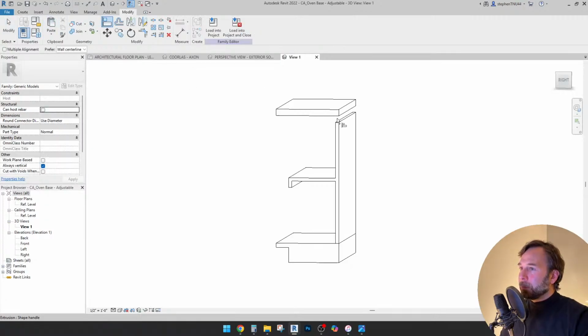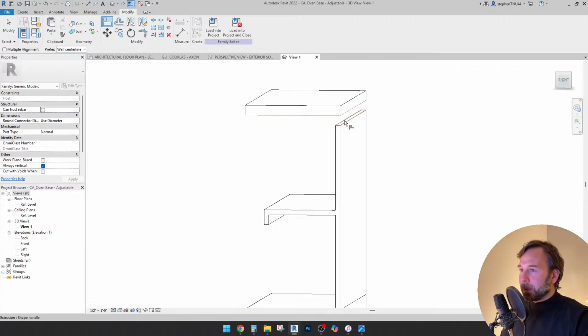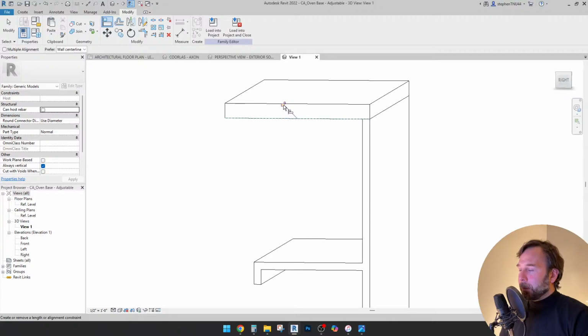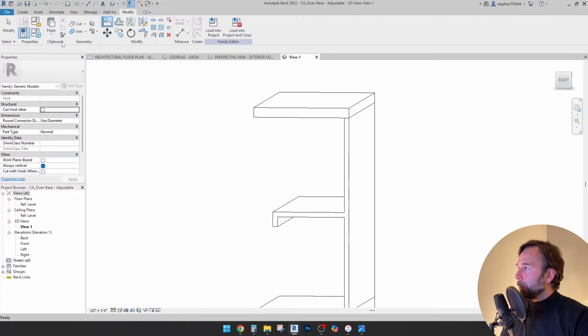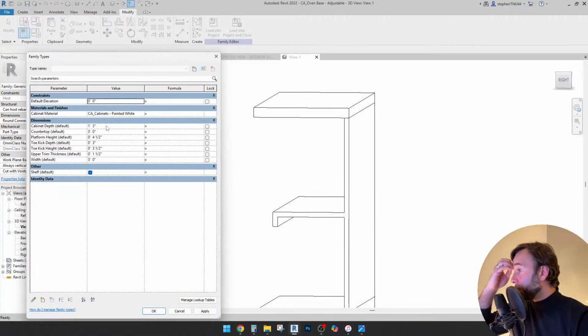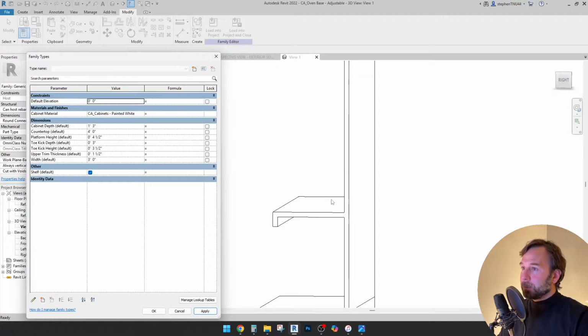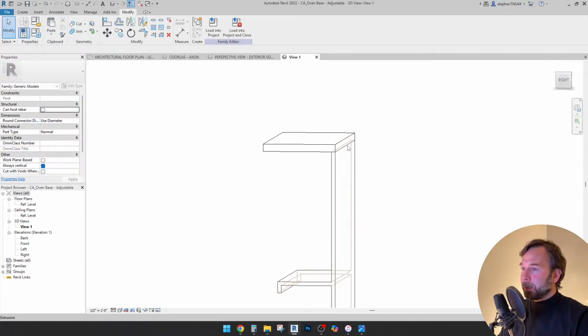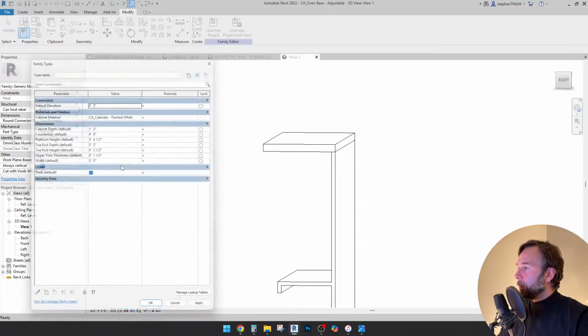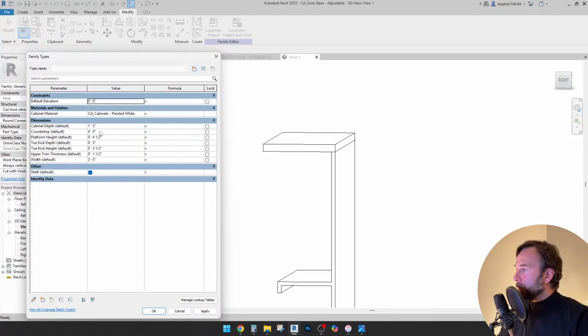So we will snap this to the underside, and if you're not familiar with components, I could do a whole separate episode training on components in Revit. But you snap it with the align tool, click that lock button, and now it should be locked. For some reason it wasn't in this model, but I can raise this up to 4 feet, and it should be sticky now.